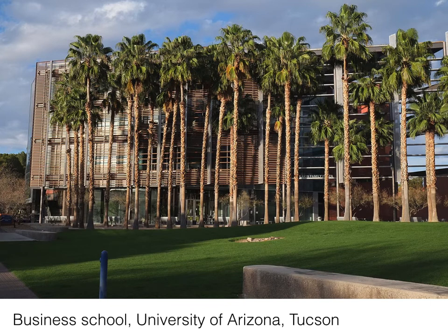The one thing that trees are not really good for is acoustics, okay? People think that they're going to plant some dense tree barrier or bushes or something and stop a lot of noise from a highway. It just doesn't work. Noise will go right between them. Noise will go through a 1-inch opening in something. So if you want to stop noise, you need something solid like a wall. Don't count on trees to do that.